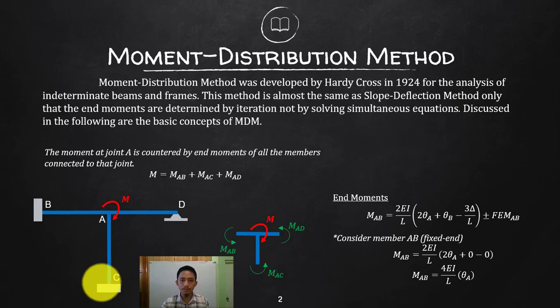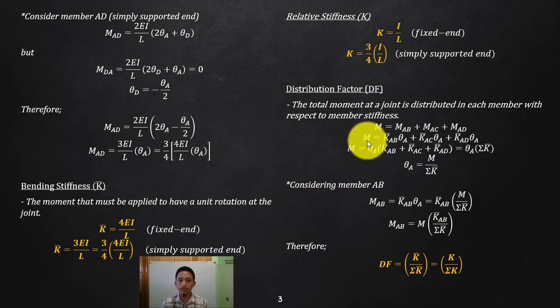So, okay, what I'm trying to say here is that, again, your total moment on the joint is distributed with respect to the strength of each of the members. So that will be in equilibrium, because you cannot just transfer all the existing moment on the joint to one member and the other one is not working.